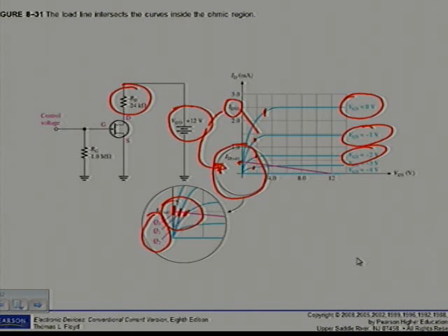So as this happens, the slope of each successive curve is less than the previous one. So a decrease in slope corresponds to less ID. You can see here, it moves in that direction, so it decreases. And at the same time, what happens to VDS? It's over here. You can see as I move along from 0 to -2, that VDS increases.